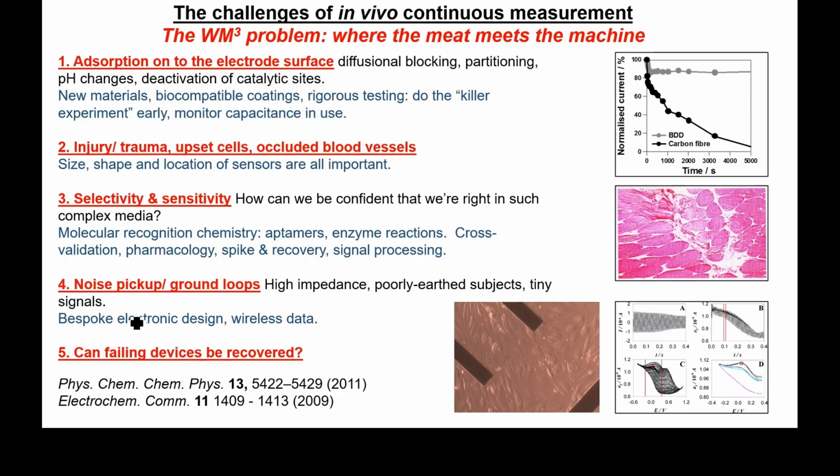We get a lot of noise. No one really knows how to ground a poorly conducting patient, where there are multiple paths to Earth, some of which are ohmic and some of which are capacitive. But wireless data is definitely the way forward, and Manos Drakakis, my colleague in bioengineering, who does wonderful electronic design, amongst many other things, did a nice paper with Martin Boutel where they showed that the noise on a wirelessly coupled sensor is so much better than when we've got cables. So good quality electronic design, talk to Manos Drakakis, consider wireless data at all times.